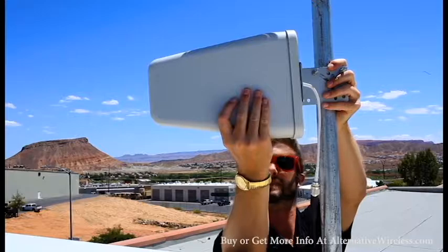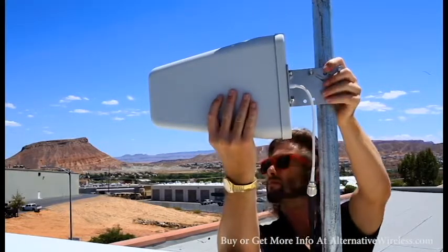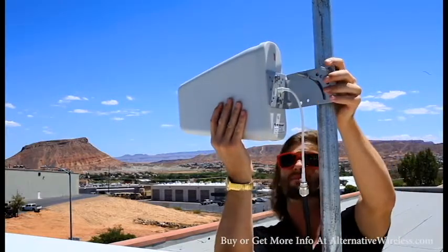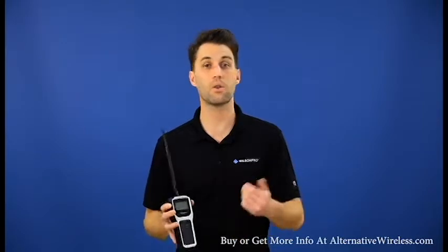Doing this allows you to make adjustments to the positioning of the donor antenna and see the results instantaneously, allowing you to find the best signal strength possible coming into the amp. From here, you have your basis for calculating your coverage area that you can expect for each carrier, and can choose the placement of your donor antenna and the orientation accordingly.